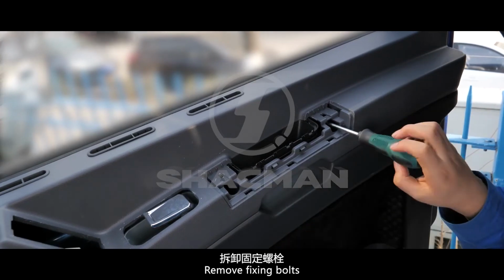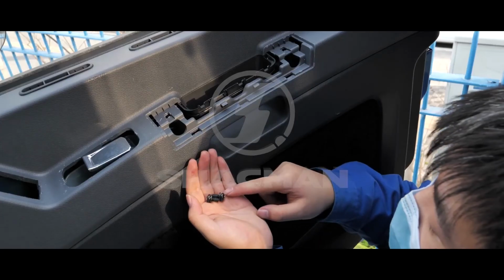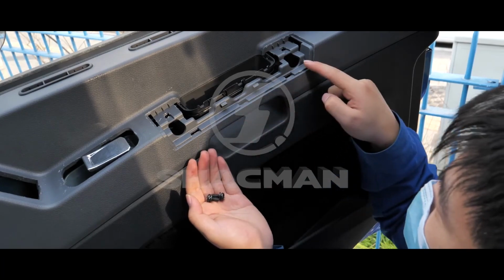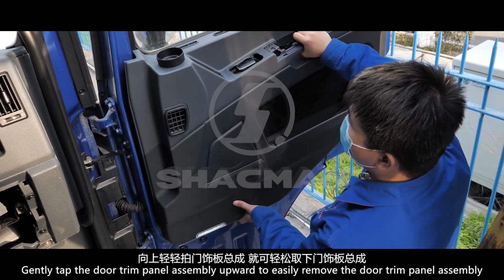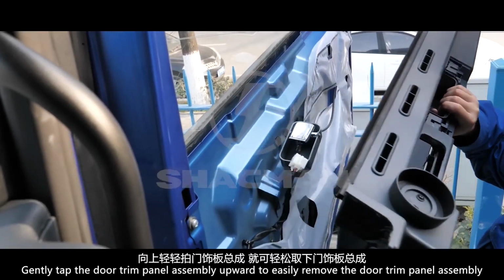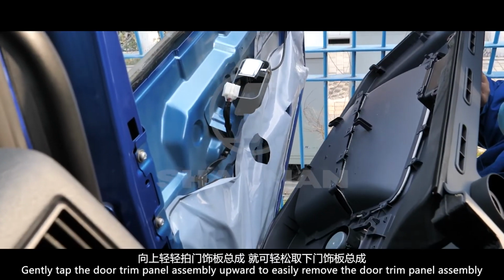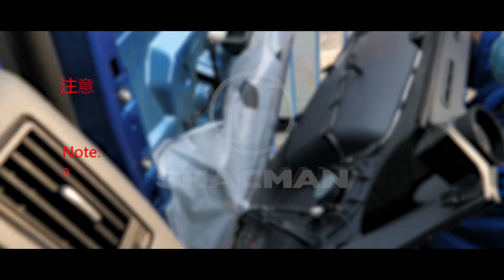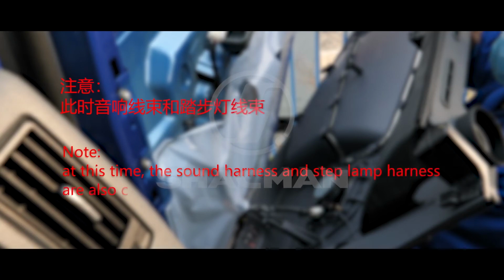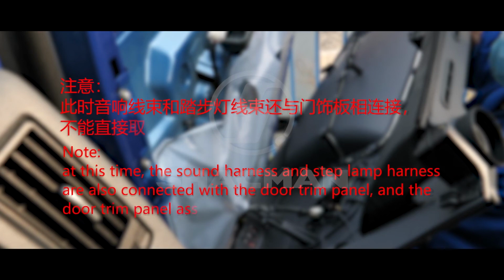Remove fixing bolts. Gently tap the door trim panel assembly upward to easily remove it. Note: at this time, the sound harness and step lamp harness are also connected with the door trim panel, and the door trim panel assembly cannot be removed directly.